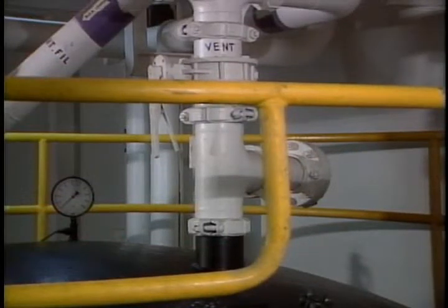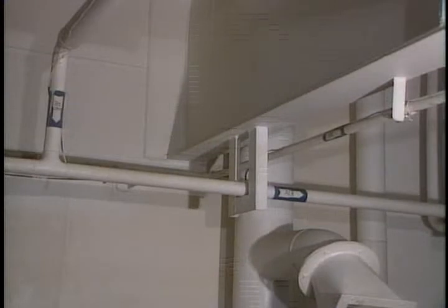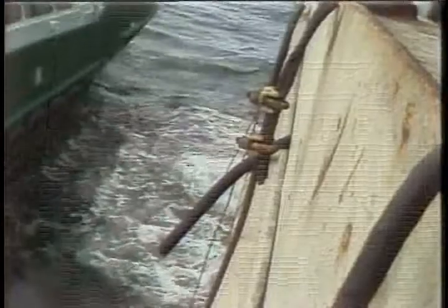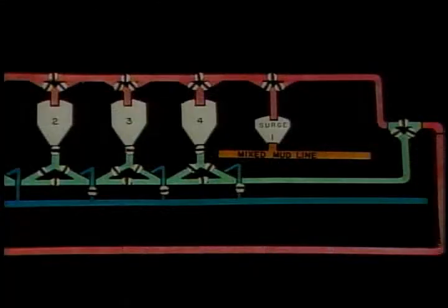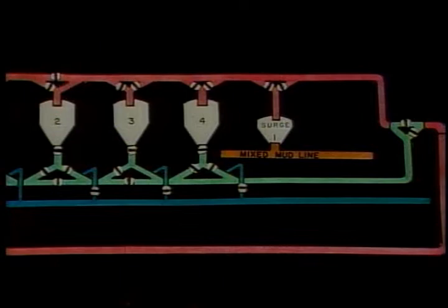The first thing that's opened is the vent line at the destination tank. This will allow the airflow to be established once all the other valves have been opened. The air generated at the source tank will travel through the system as you have it routed. Then it will be vented overboard from the destination tank. When the pressure in the source tank has reached its operating pressure, the proper valves can be opened to direct the material from the source to its destination. Before opening the discharge valve, get your airflow started by opening the purge air at the source tank.